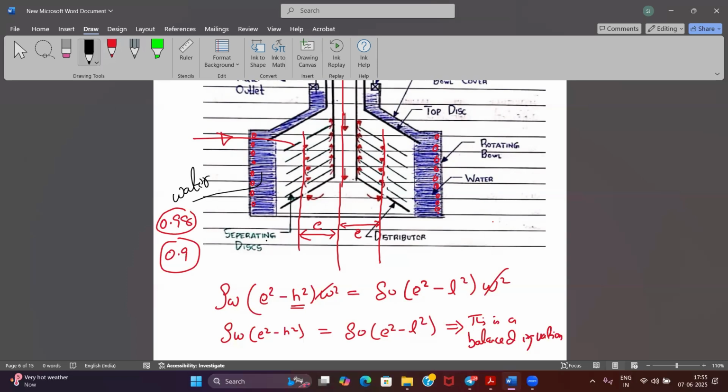Yes sir, we will run the purifier as a clarifier in that case. No, we will change the gravity disk. Wait. The purifier will be changed to a clarifier in one state, if the density is going above one. Number one. The rest, if the oil density changes, is the gravity disk only. If the oil density is going above one, then you should run those purifiers in clarifier mode. Clear? Always remember that.